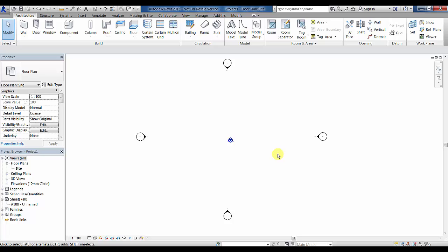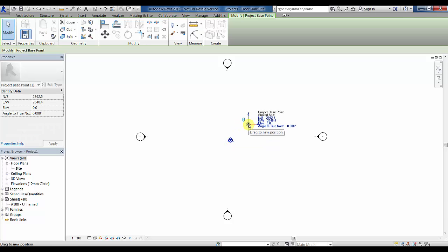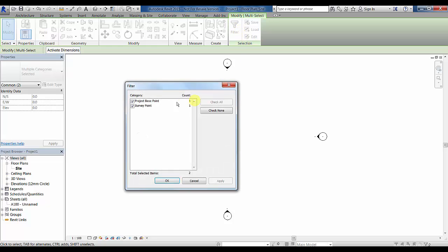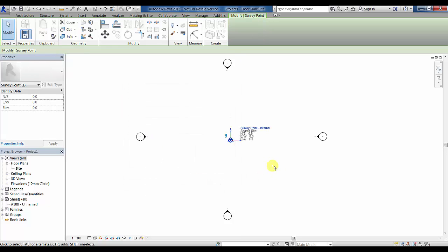Okay, now I really need to give you a quick basic explanation of the Revit coordinate systems. There are actually three different coordinate systems within Revit. The program's internal coordinate system, which it uses to define geometry and is not visible or editable. The second is the survey point, which is the triangle we looked at, which defines a known physical position in the real world and is used as the basis for linking multiple models by shared coordinates. This is going to be used to give our true north for the survey and anchors us in the real world. The third is the project coordinate system, or the project base point.